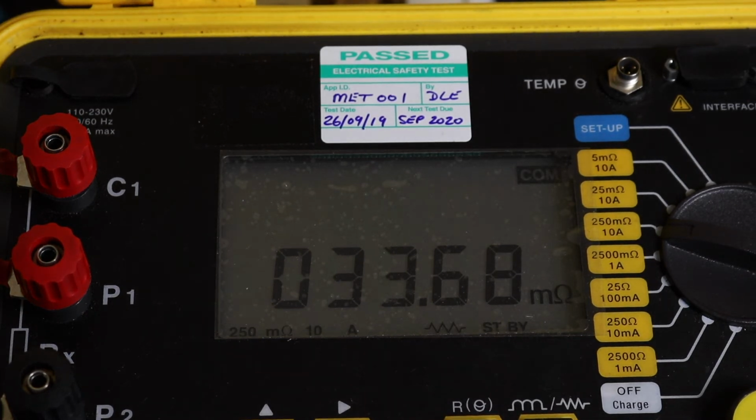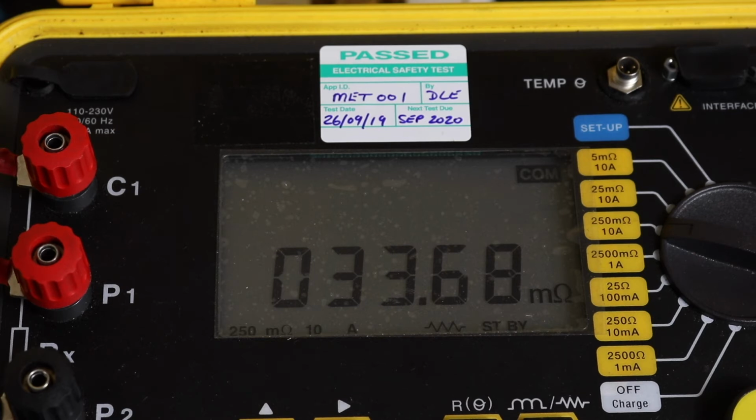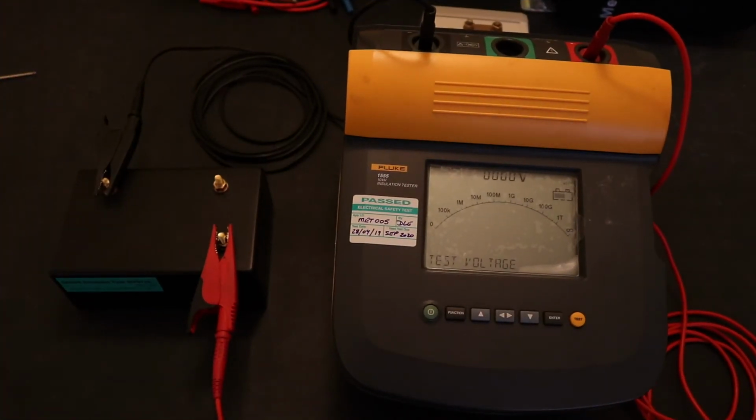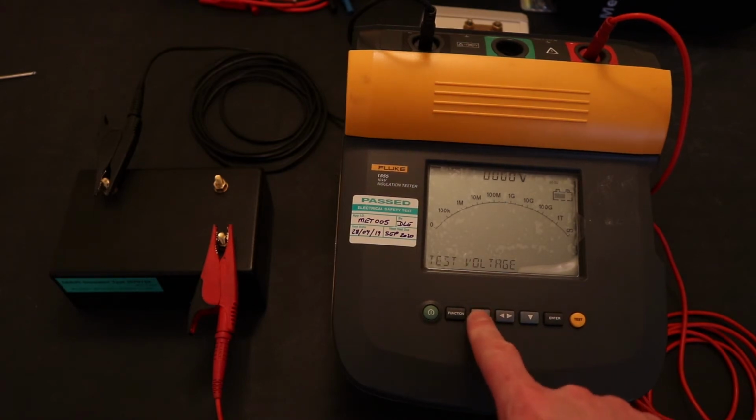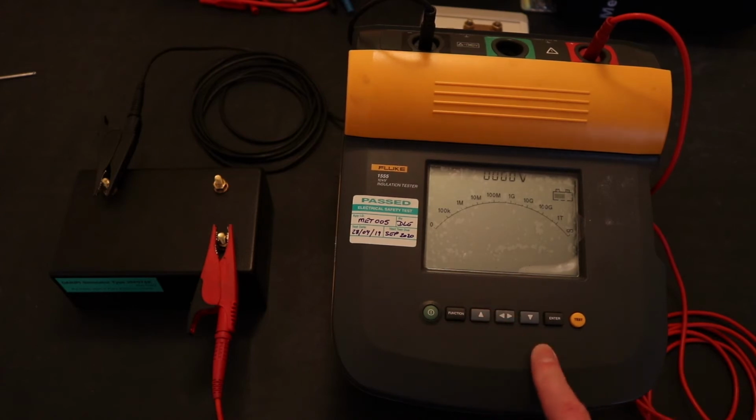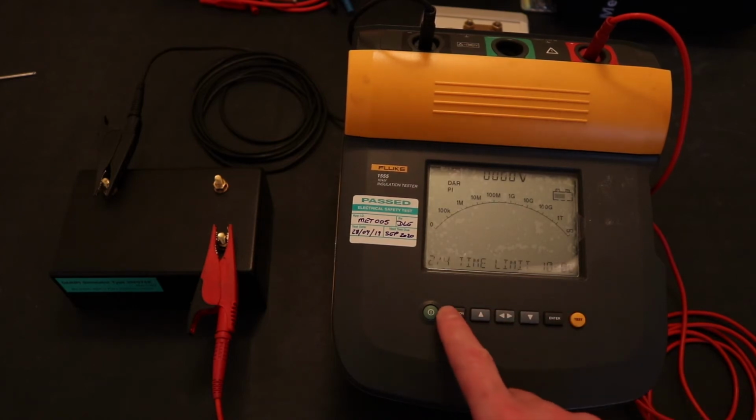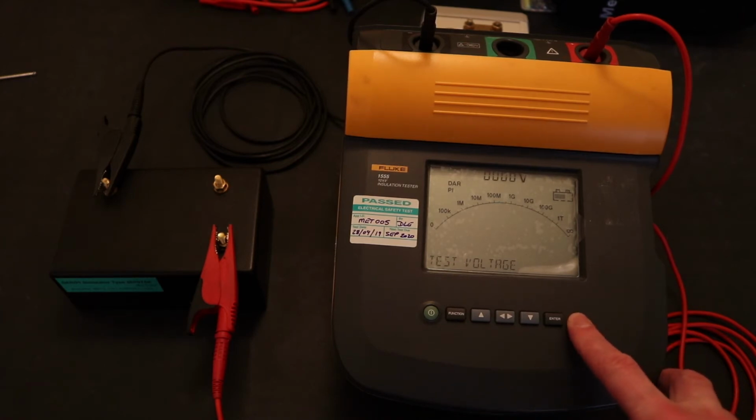What I'll now do is I'll set up an insulation tester and I'll go for a polarization index test on the unit and see how that comes out. This is the Fluke 1555 insulation tester I'm using. It will go up to 10 kV, but I'm only taking this up to 5 kV, otherwise the capacitors will not like it. I'll change it to the polarization index test there. And my voltage is 5 kV. And we hit the go button.